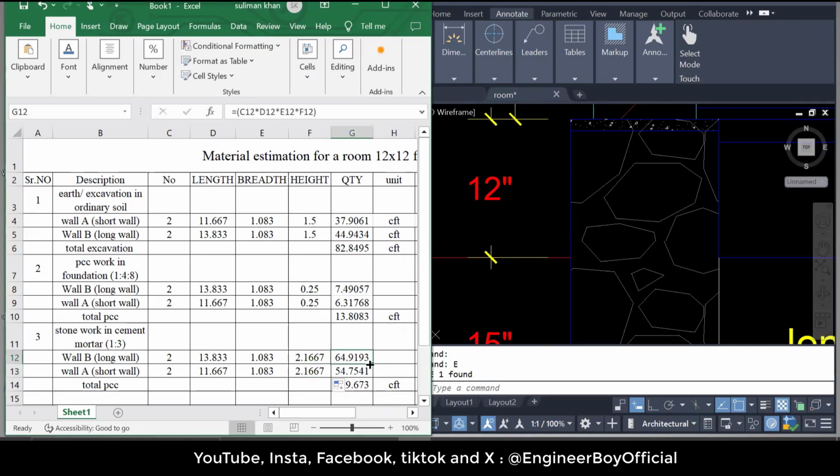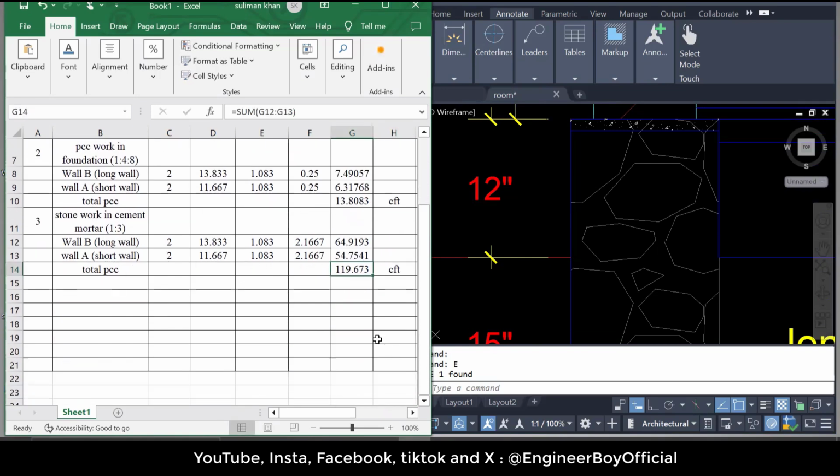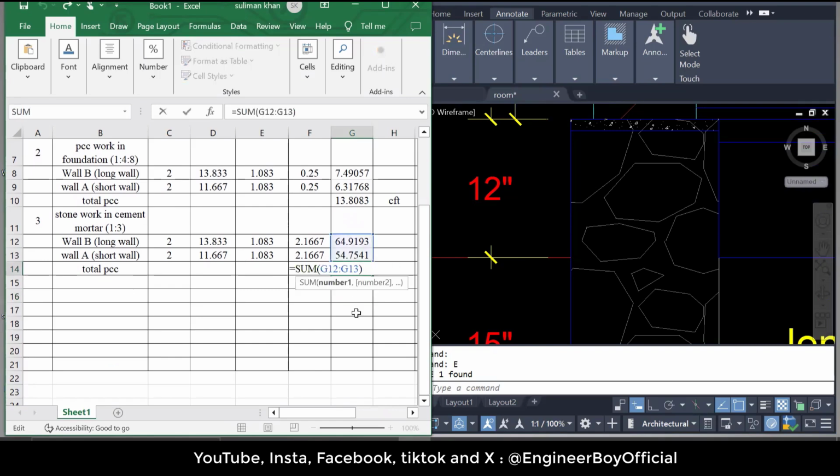And the formula was just pre-applied. So this is 64 and 54 as the stonework, okay? And this is actually the summation in CFT. So the stonework is how much? It is 119.673 CFT, okay? Now from this stonework, further we have to determine the...